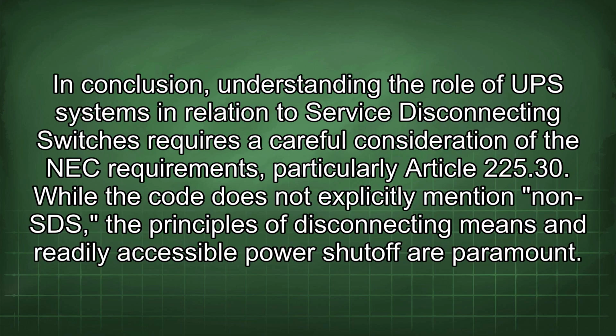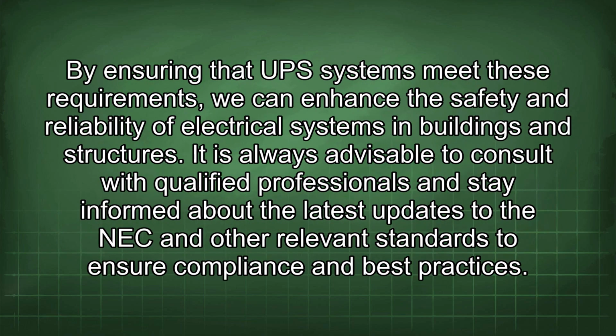In conclusion, understanding the role of UPS systems in relation to service disconnecting switches requires a careful consideration of the NEC requirements, particularly Article 225.30. While the code does not explicitly mention non-SDS, the principles of disconnecting means and readily accessible power shutoff are paramount. By ensuring that UPS systems meet these requirements, we can enhance the safety and reliability of electrical systems in buildings and structures. It is always advisable to consult with qualified professionals and stay informed about the latest updates to the NEC and other relevant standards to ensure compliance and best practices.